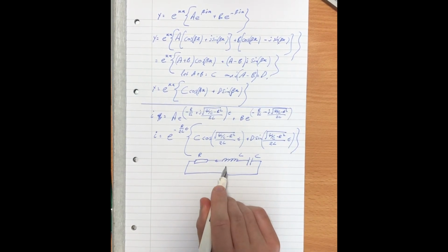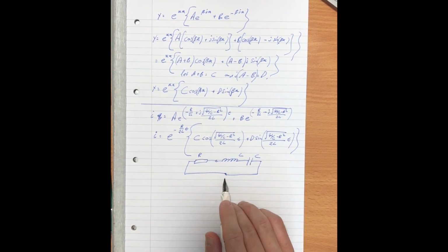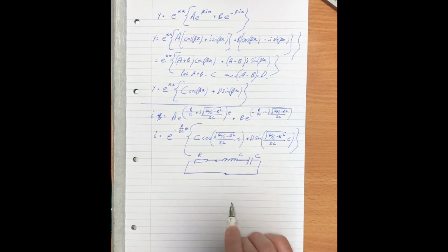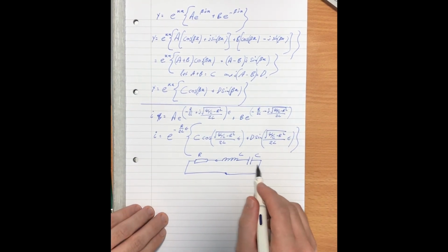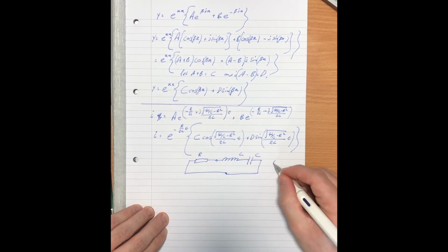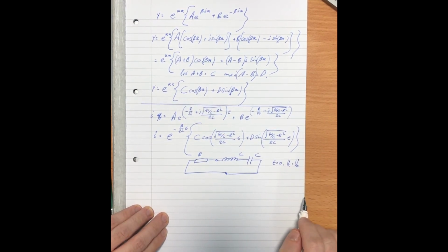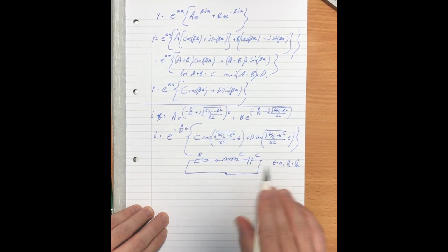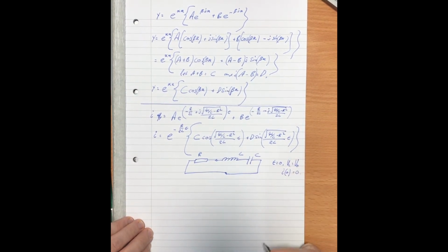So let's think about this. This is where you really need to be very, very careful. When t equals 0, the current should be 0. Is that correct to say that? When t equals 0, the current is 0. Well, when t equals 0, the voltage across the capacitor is going to be some initial voltage, say V0. At that point, the current should not be flowing. It's about to flow, but it shouldn't be flowing. So we can say that i0 equals 0.